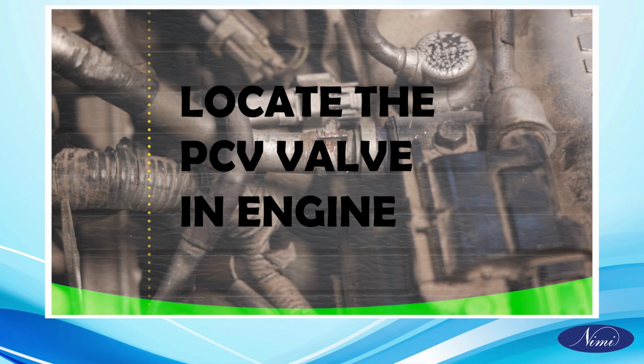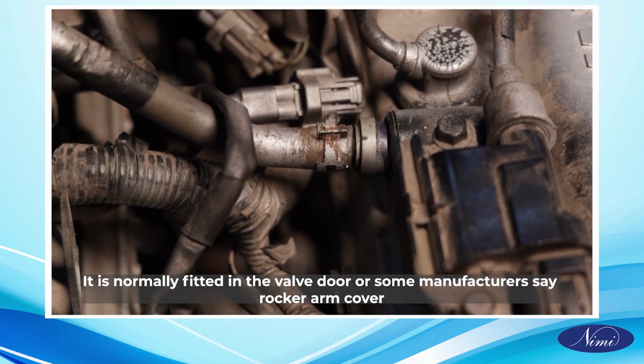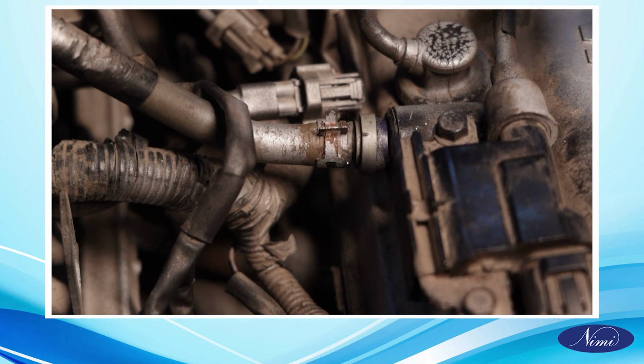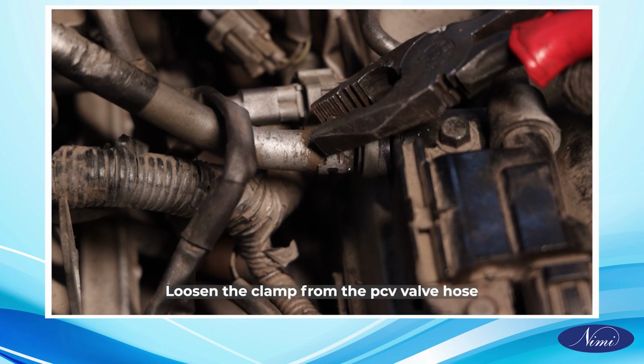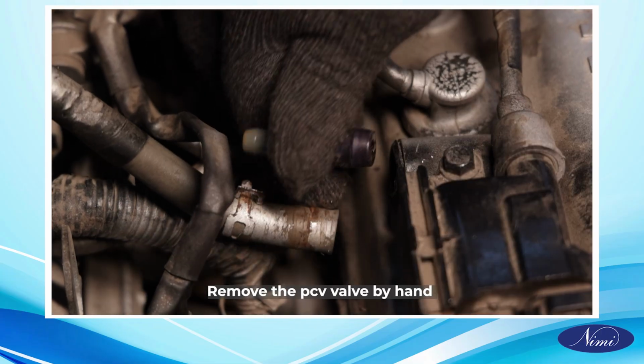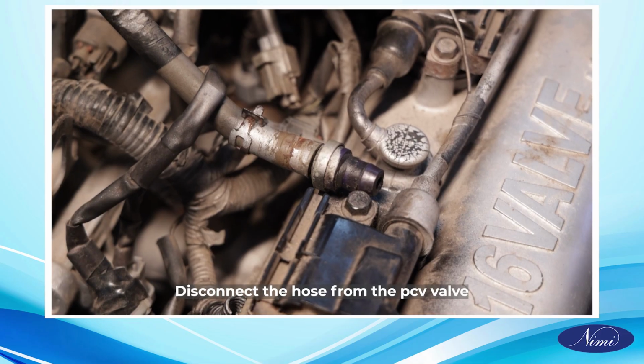Locate the PCV valve in the engine. It is normally fitted in the valve cover, or rocker arm cover as some manufacturers say. Loosen the clamp from the PCV valve hose. Remove the PCV valve by hand. Disconnect the hose from the PCV valve.